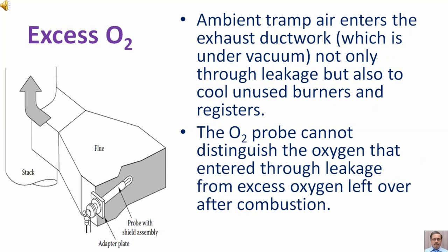Ambient tramp air enters the exhaust ductwork not only through leakage but also to cool unused burners and registers. The oxygen probe cannot distinguish the oxygen that entered through leakage from excess oxygen left over after combustion.